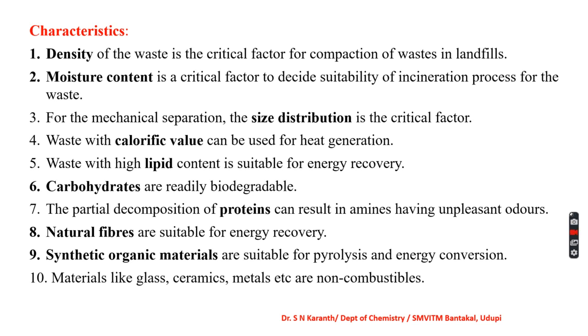Waste with calorific value can be used for heat generation. Some waste can give heat, so we can use it in order to generate heat. Waste with lipid content is suitable for energy recovery. Carbohydrates are readily biodegradable, so we can dispose of them in the form of compost. The partial decomposition of protein can result in amines having an unpleasant odor. Natural fibers are suitable for energy recovery. Synthetic organic materials are suitable for pyrolysis and energy conversion. Materials like glass and ceramics are non-combustible.